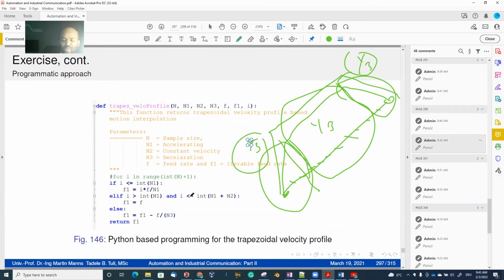Okay, so if you command stop, the machine will only start to think about stopping after 2 milliseconds. It doesn't react immediately. So you have to think if this could really affect your process, because it could, right? If it doesn't stop where you want to stop it, then it is still a problem, right? So this is what you have to consider. But more or less you have an option to decide.